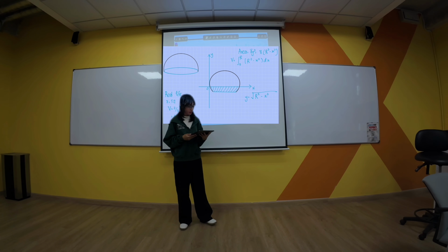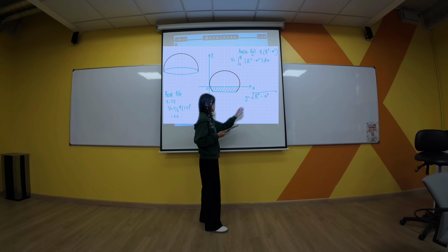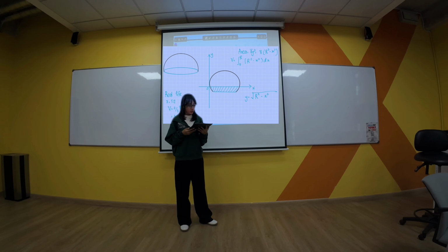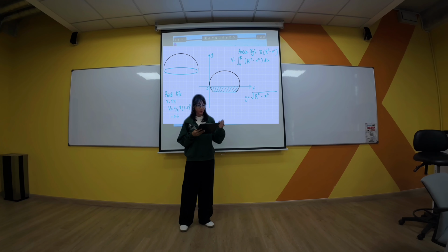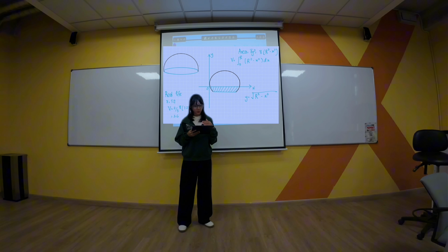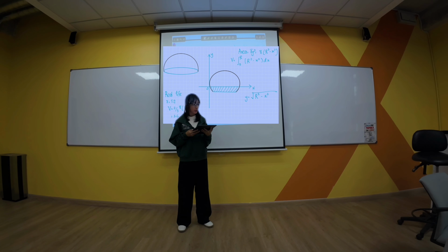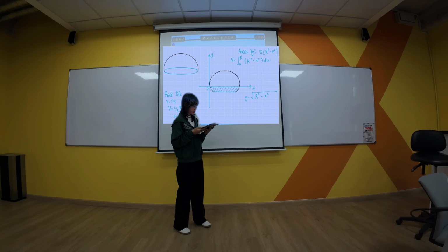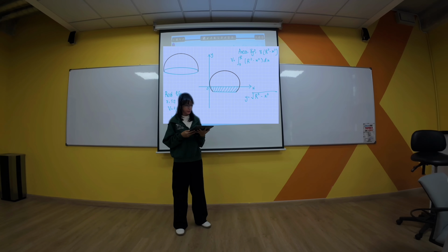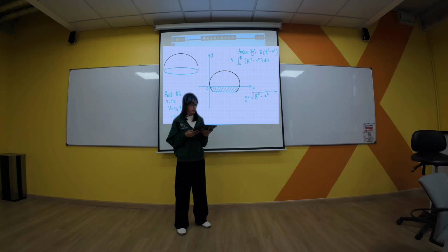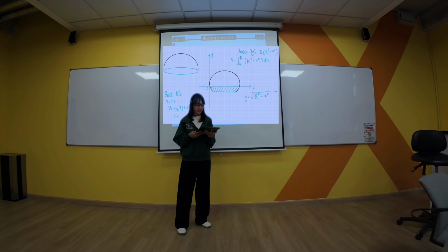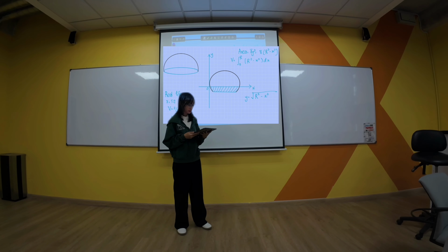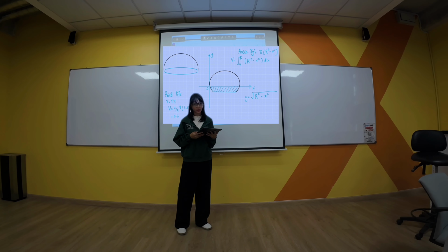We start with the equation of a semicircle, and our formula will be this. The top half of the circle is represented with a radius of r, and I will only look at the right side, from x equal to 0 to x equal to r, because when we rotate this part around the x-axis, it will form a complete hemisphere. When this semicircle region spins around the x-axis, the shape created is the hemispherical fuel tank. This is how we model real-life tanks, using a simple equation and a rotation in 3D.